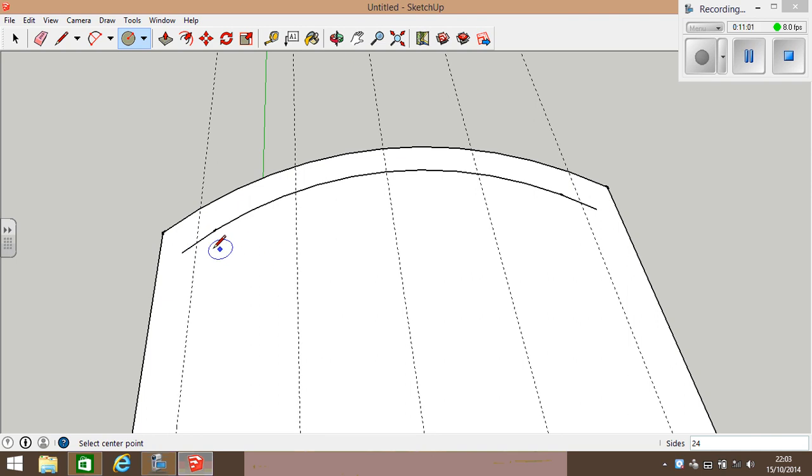First of all, we're going to start off at that intersection where that very first line is. We're going to draw a circle, pull it out a little bit and press 10 and enter. And we're going to do this exactly the same on all 5 of these points.